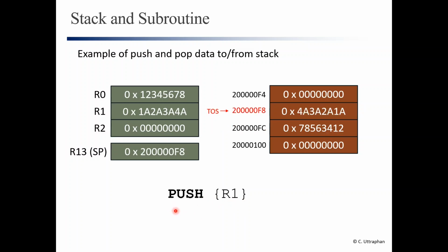Next, when we push the content of R1 into the stack, the TOS is now updated to 200FFFF8, where the value from R1 is now in the memory address 200FFFF8 to 200FFFFB. Observe the value in SP, it will always point to the TOS.